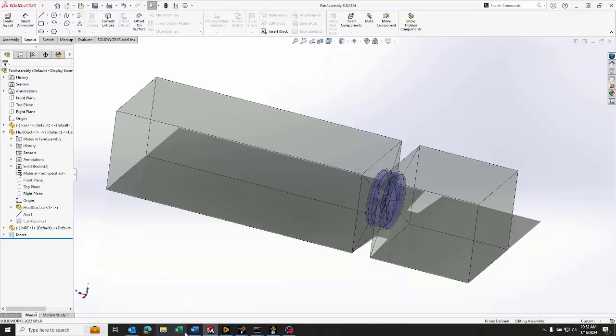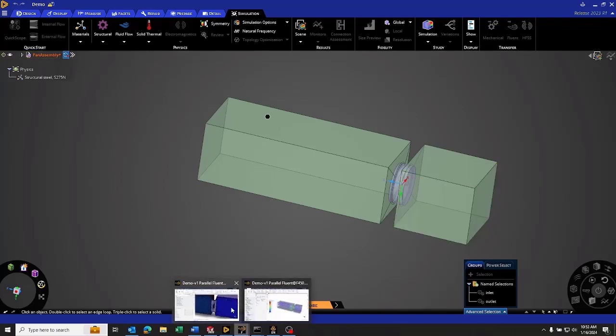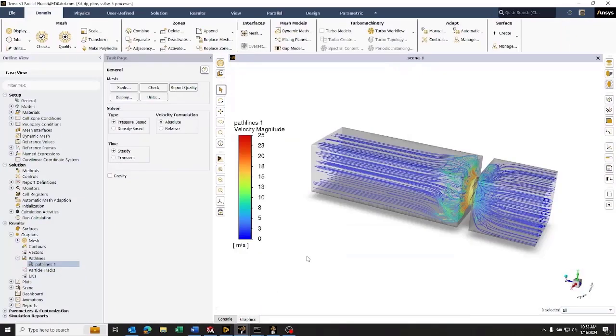In our first design, we took the geometry over into Ansys Discovery, applied our name selections, which are our flow boundary conditions, as well as shared topology to create watertight regions of space. We passed this over into Fluent meshing, where we used the watertight geometry workflow to create a highly efficient mesh. We brought that mesh into the solver, set up our boundary conditions, and solved our model. We looked over the results and saw that while the performance was good, we'd really like to improve it.